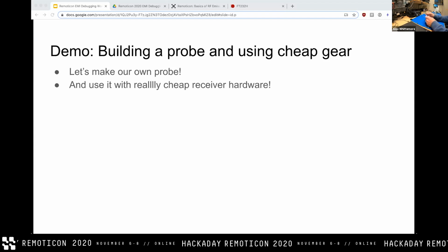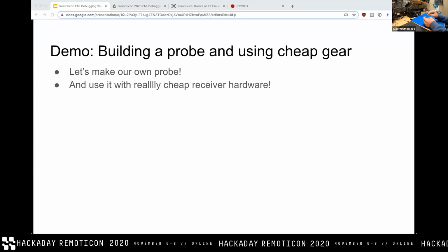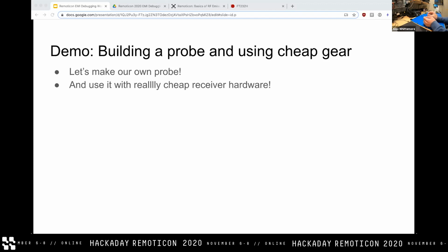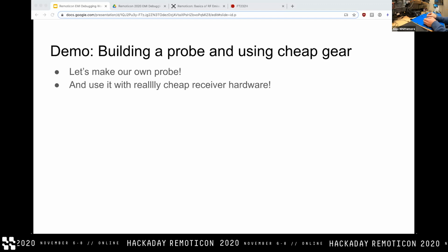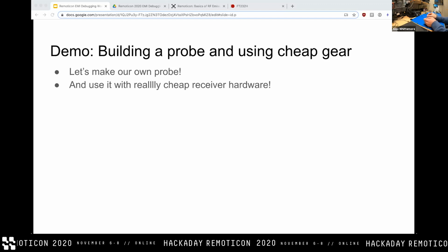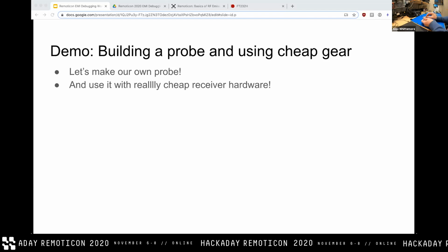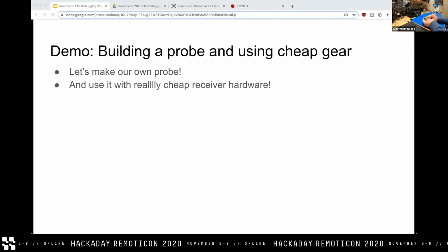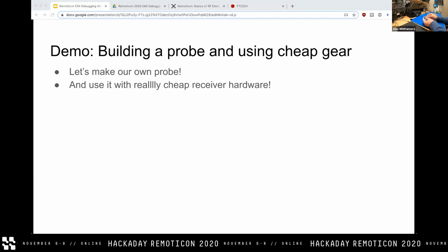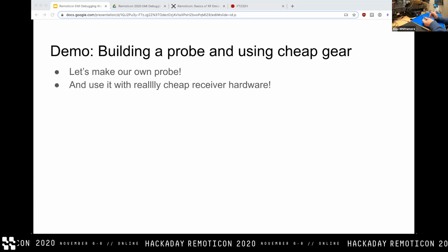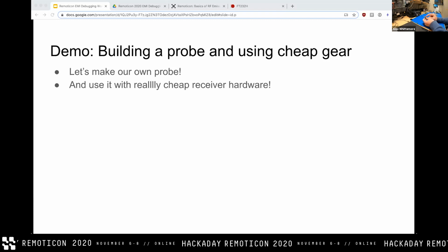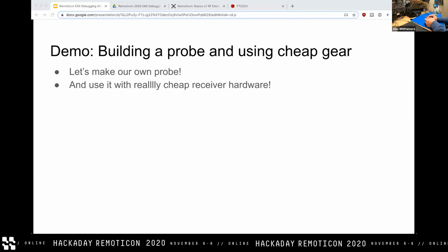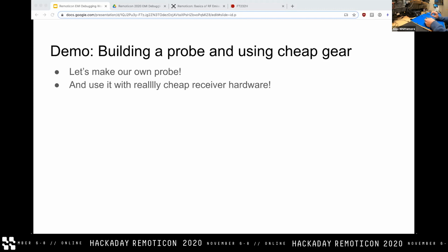Very critical point here is that there's a DC voltage on this pin out of the SDR right now. So what we definitely don't want to do is plug in our probe without the LNA. The LNA has a DC blocking capacitor on the RF input side, so that no DC voltage from the power supply circuitry of this guy leaks out into your antenna or anything like that, which is important because these are DC shorts to ground.